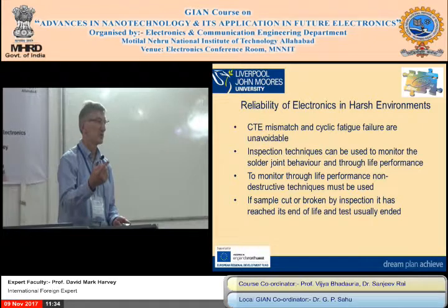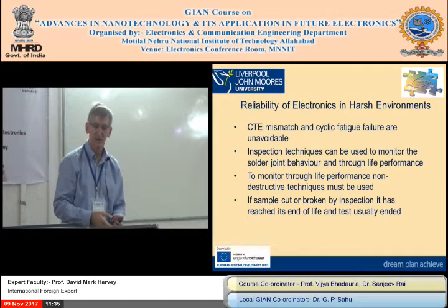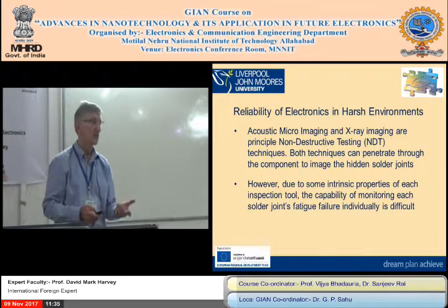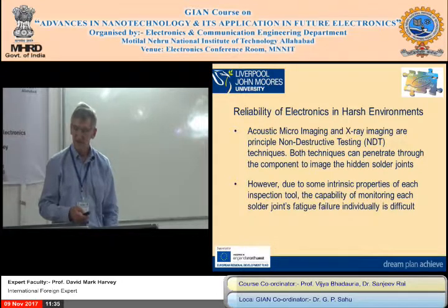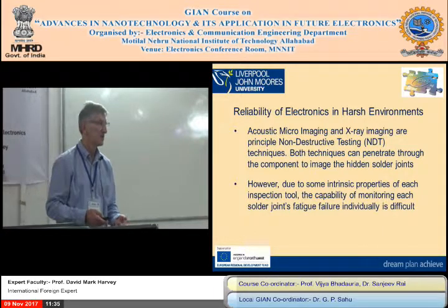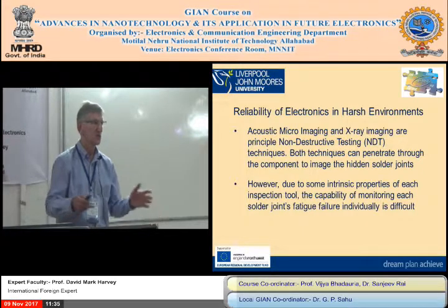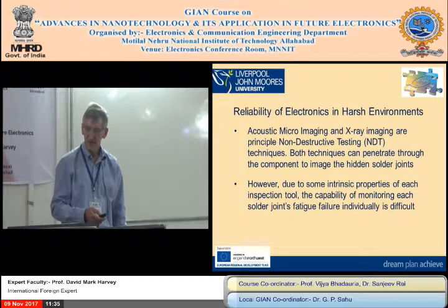So you've got electronic probe on electronics. If you want to look at the physical cracks, you need some other method. We didn't have it available, but we have tried it at another university. 3D X-ray, like X-ray tomography, is coming in, but it's very expensive. That is another method. So just to reiterate there, AMI is acoustic microimaging. We call it ultrasound inspection. And we're using that with X-ray inspection, join the two together in some data fusion, and we get the best of both worlds.